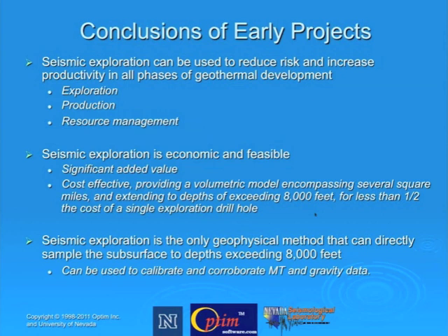So after these early projects in the 90s, we could conclude that seismic exploration can reduce the risk and increase the productivity in all phases of geothermal development: exploration, production, and resource management. Seismic exploration is not only effective, but it is economic. It is feasible. It's giving us now, with the SeisOpt technique, significant added value, and it's cost effective. We can make these volumetric models encompassing many square miles, and extending to great depths, for much less than it costs to drill a single hole.